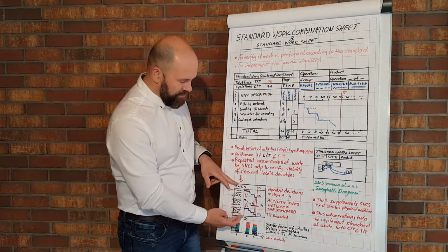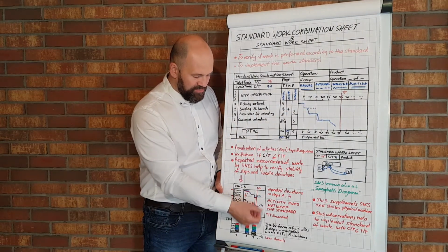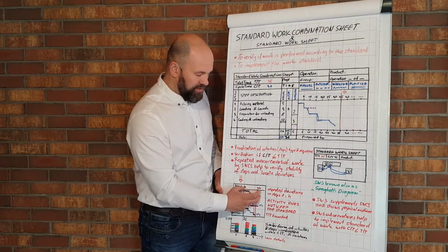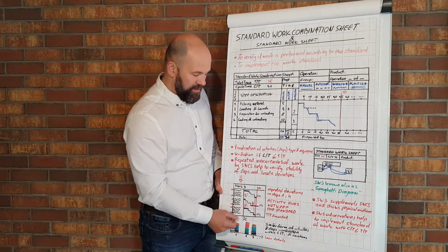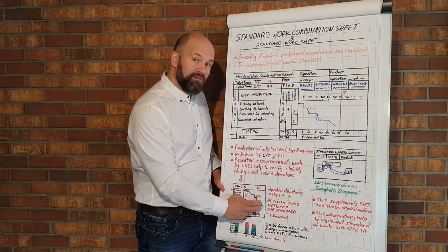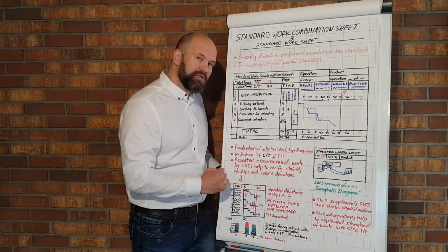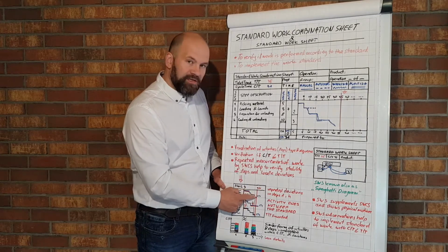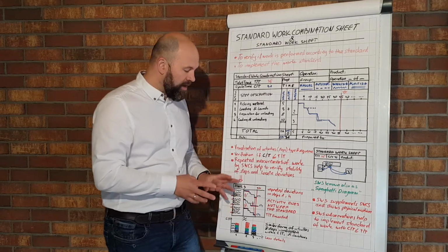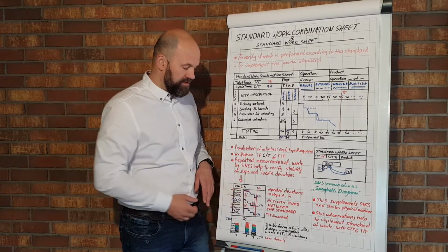If you repeat the same observed sequence of steps, and if you repeat the measurements and observations, you may check if you keep the standard, because if the total cycle time is different, you may conclude that you don't keep the standard in your process, especially if the deviation is big. If it exceeds the takt time, the problem is even bigger, because you need to squeeze it to be on time. And by this visualization, you have precise information which steps in your process are problematic ones, and you can address your actions directly to these steps to optimize.